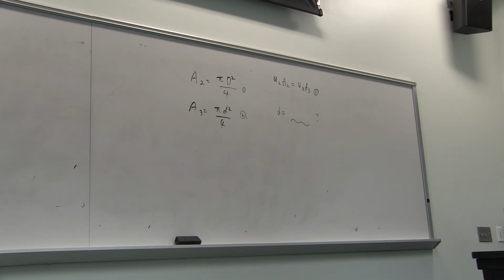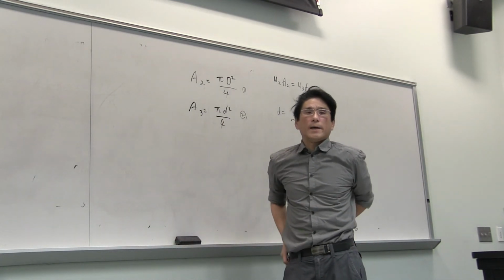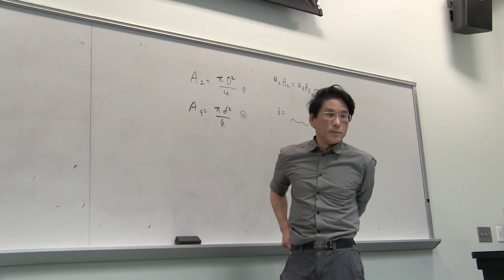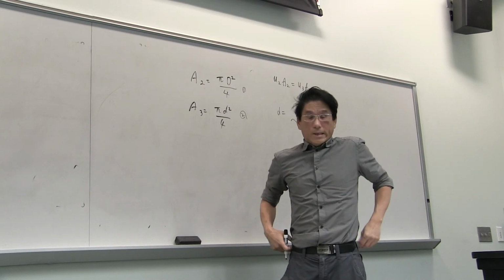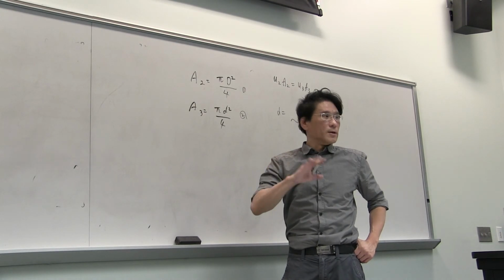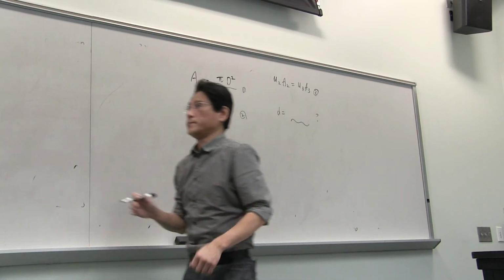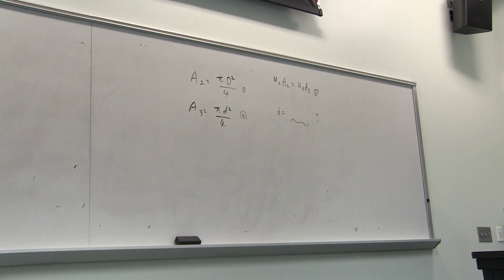What is acceleration? Before you do anything, think about how you get the acceleration. You have to differentiate u with respect to time, but this should be the material derivative. The material derivative only works in fluid mechanics. When you think about the Eulerian description, you're talking about material derivatives, which is just capital D over Dt.